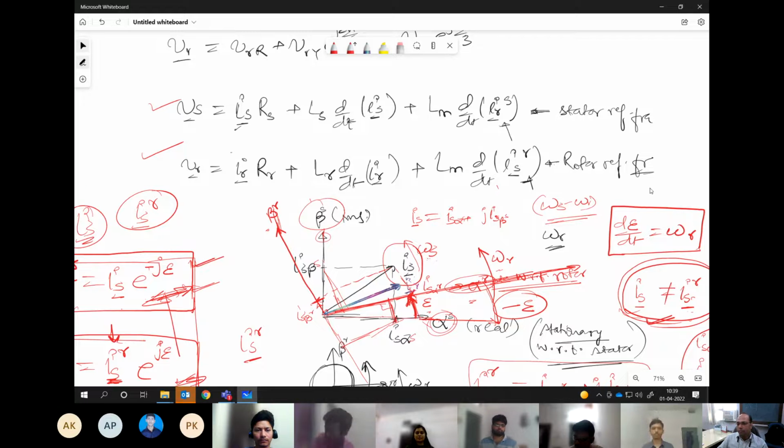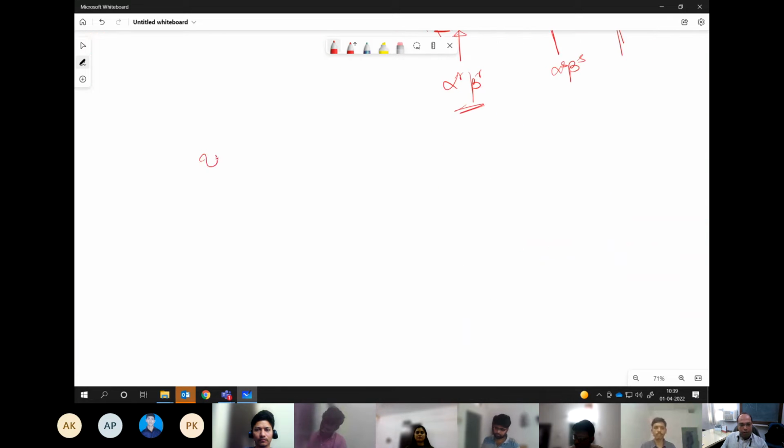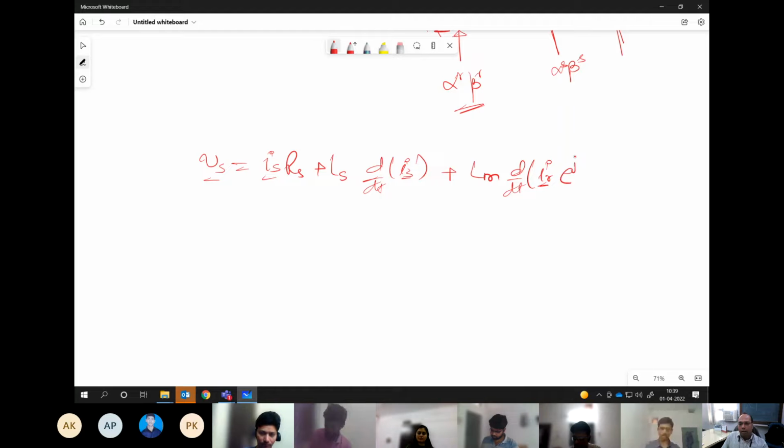You understand my point? So what I will write? Now I will write my voltage equation as Vs equals Is Rs plus Ls d/dt of Is plus Lm d/dt of IR multiplied by e to the power j epsilon. Now everything in this equation is known. We can measure IR, we can measure Is, we can measure Vs, we can measure epsilon, the angle. So epsilon, again I am saying that d epsilon by dt, or rate of change of this angle, is basically omega r, at which the rotor is rotating.